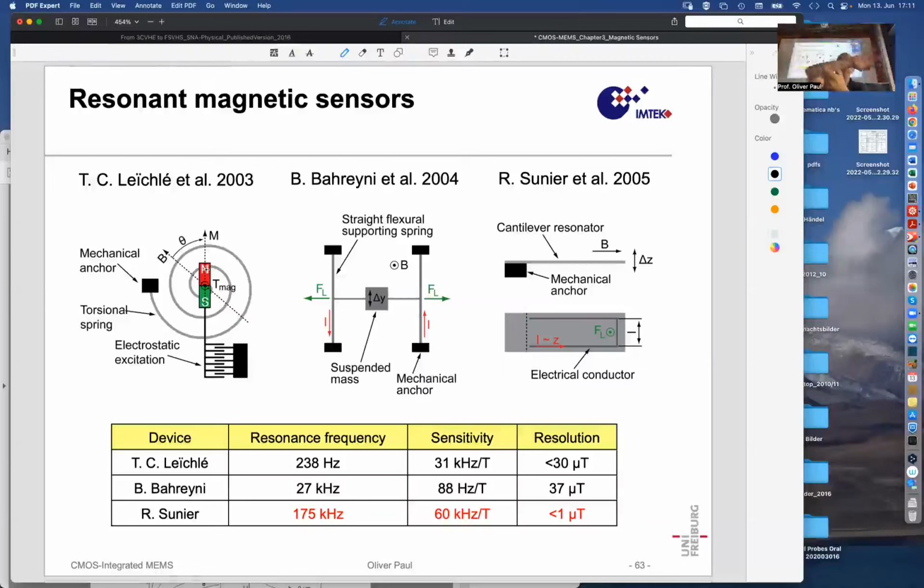So in one direction, the resonance frequency is increased, and in the 180 degree direction, the resonance frequency is decreased. And so you can rotate the device, and then you can measure the resonance frequency, and where the resonance frequency is maximum, you know the north is there. So that is the principle of this device.